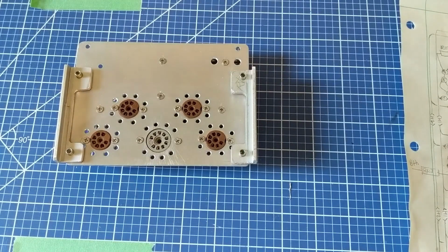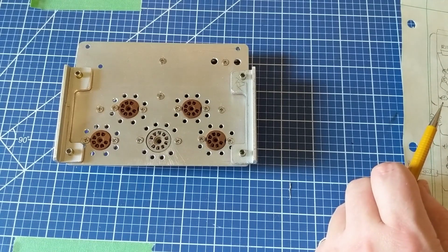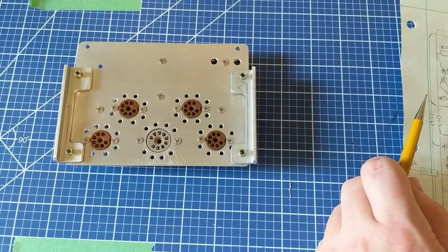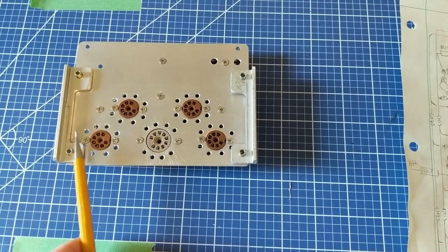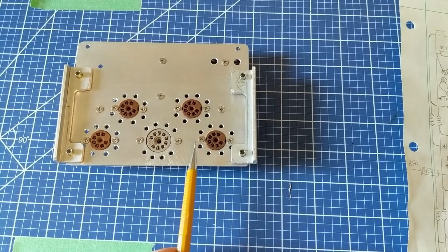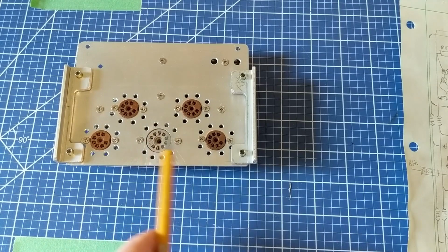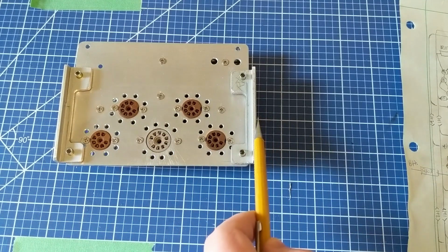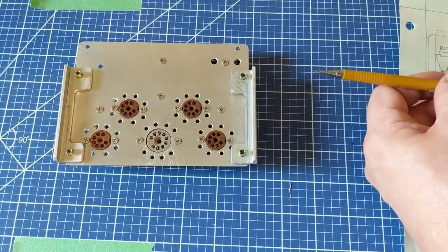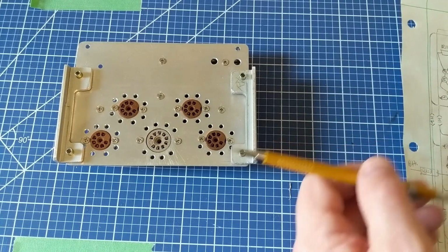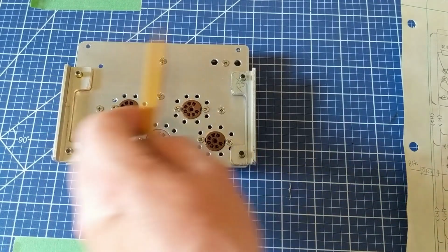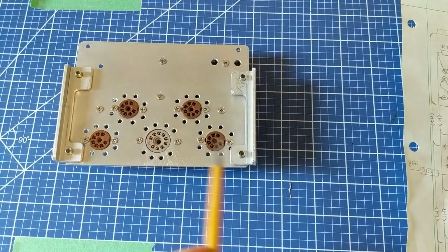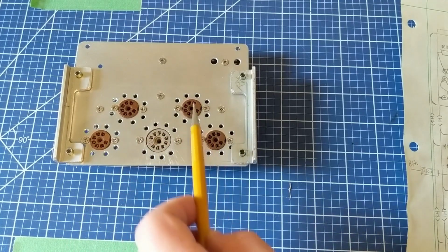This is the subplate that I came up with for the amplifier. As we talked about in a previous episode, this is the plate that sits just under the surface of the chassis on the top side, and it's used to hold all of the sockets for the tubes. These two pieces on the side will be tapped and threaded into the side of the chassis, and it'll use this to hold it securely to the inside of the chassis. So there's no holes in the top of the chassis other than the ones needed to have the tubes poked through.